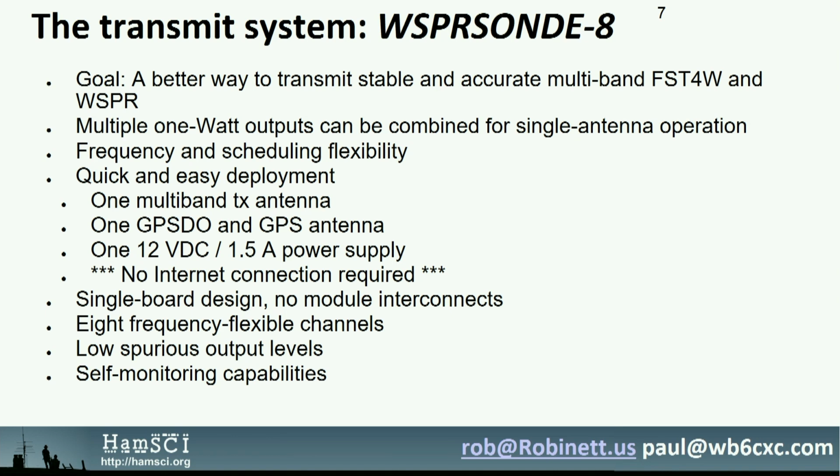So generally, we're using an 80-meter end-fed half-wave antenna. That's going to have decent resonances or matches on pretty much all the harmonically related ham bands above 80 meters. Not everybody used that, but a lot of us did. I'm using those myself.